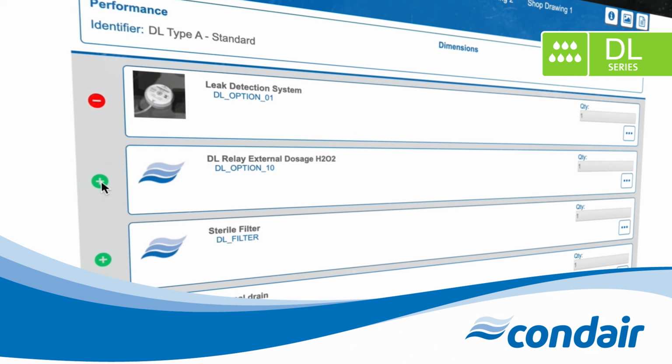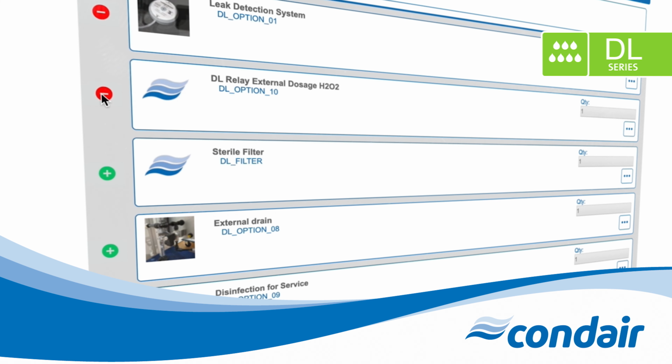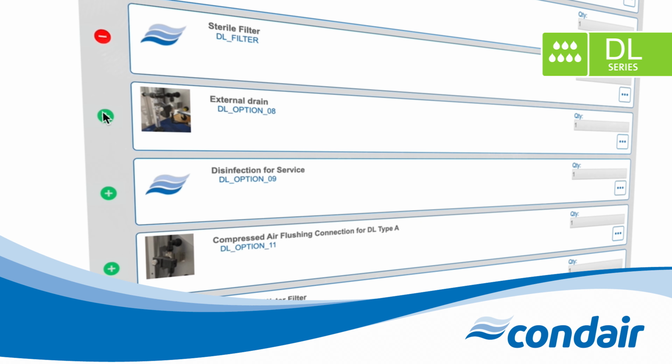The external dosage relay allows for germ neutralization using hydrogen peroxide rather than silver ions. This is typically used for painting applications, but is also a good option for users who do not wish to use silver ion neutralization for other reasons. The sterile filter with automatic self-monitoring is a 5-micron filter installed upstream of the booster pump, which helps to extend the life of the booster pump and provides additional hygiene safety.